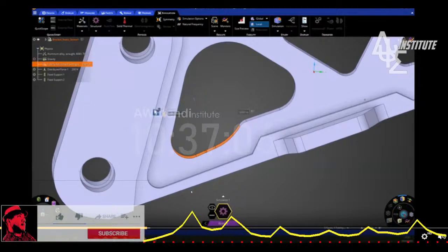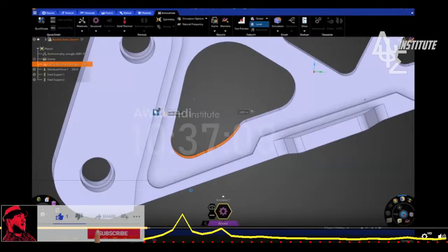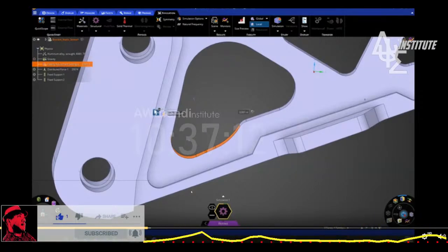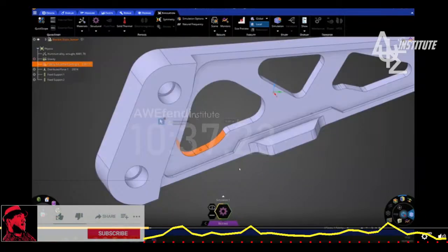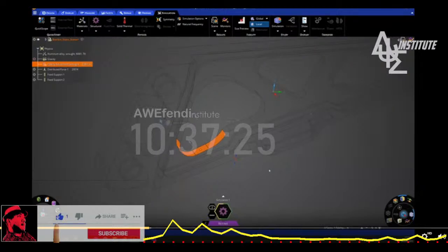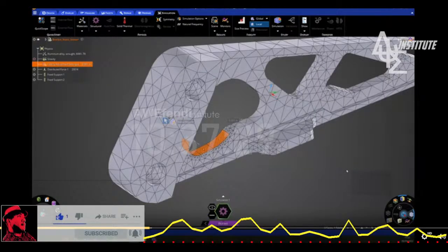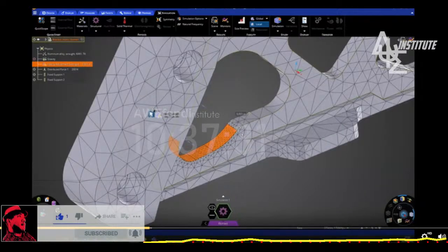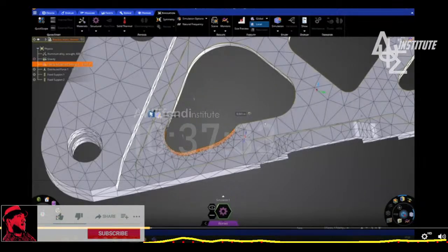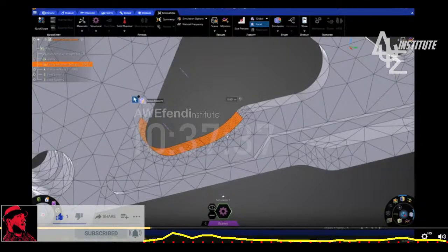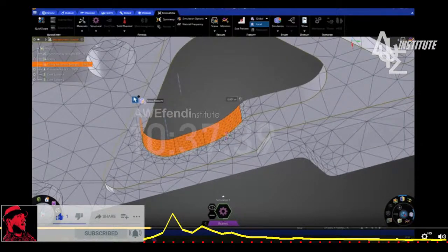The very first thing that you notice is that the simulation takes a bit longer to run. As Janosch mentioned, the refine mode uses our flagship Mechanical solver under the hood, which is why it's taking a little longer. And you can already visualize the mesh, and you can see the mesh is coarser in the other areas, but I would like it finer in this area, which I have been able to achieve using the local fidelity option.